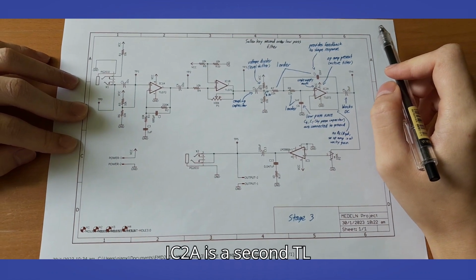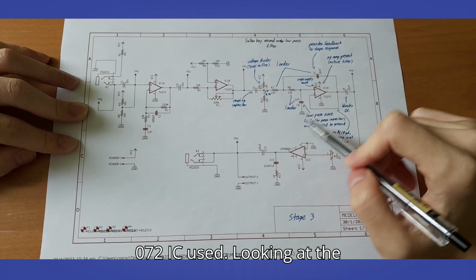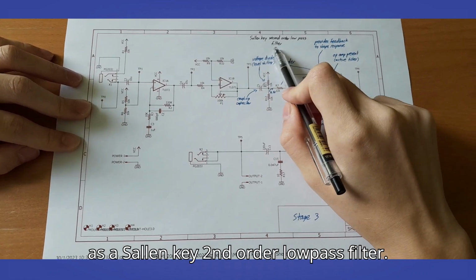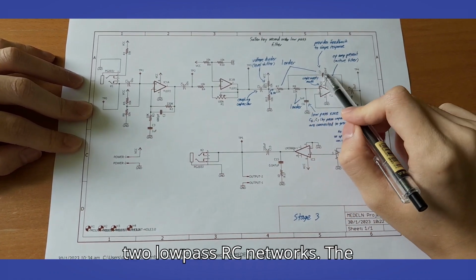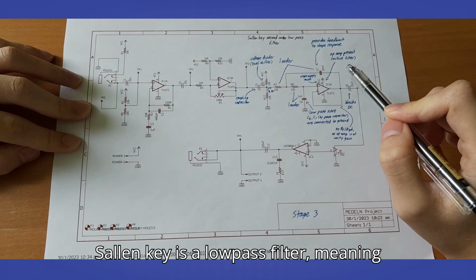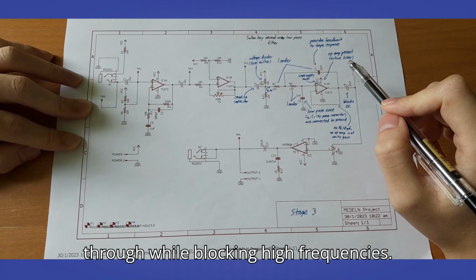The IC2A is a second TL072 IC used. Looking at the configuration of the stage, it is patched as a Sallen-Key second-order low-pass filter. It is second order since it is made of two low-pass RC networks. The Sallen-Key is a low-pass filter, meaning it will allow low frequencies to pass through while blocking high frequencies.